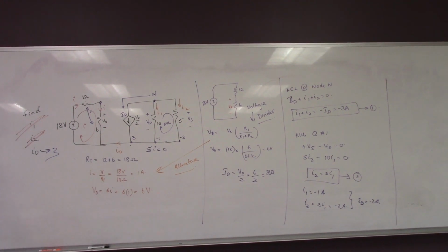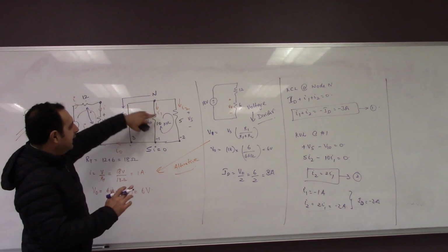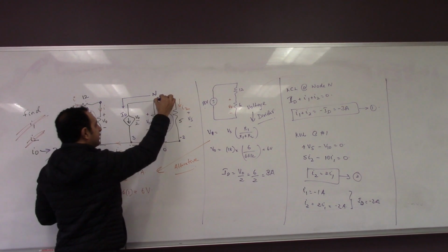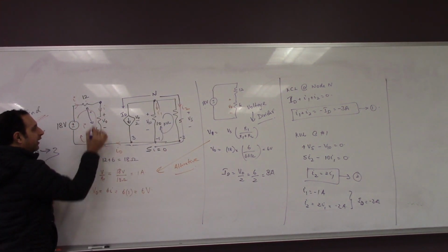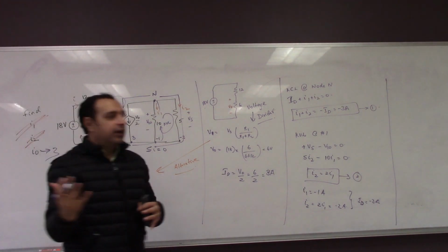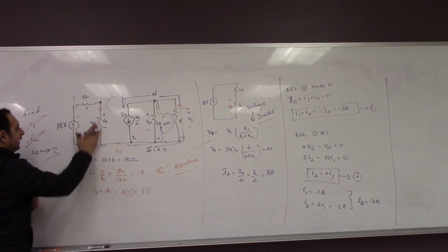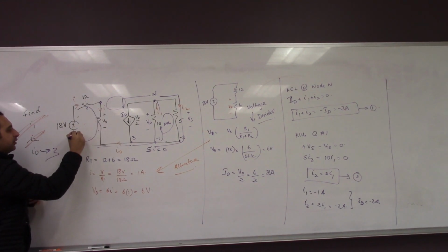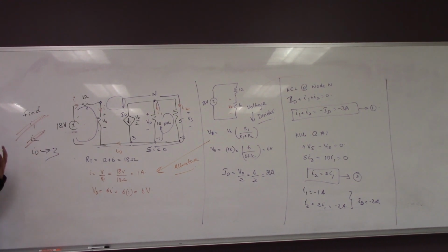And why is that? See, whenever you look, you don't even have to do any of it. Just look at any current, right? If the current enters from here, it leaves from here, right? If this current is entering from this end, it's leaving from the other end. If the current goes this way, how is it going to come back? Because there is no connection here. Okay? So, for a current to flow, there should always be a closed loop. So for example, if I0 is going this way, right? It has to go around and come back to the source.